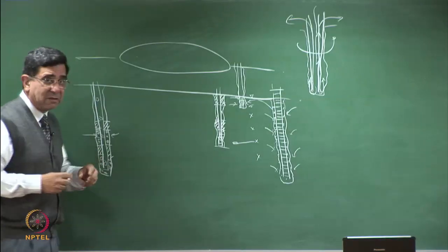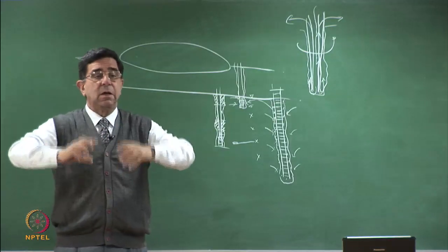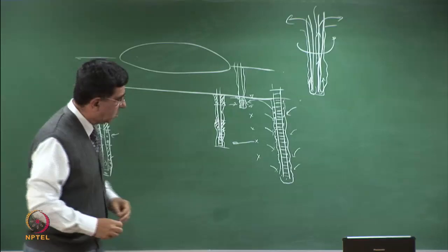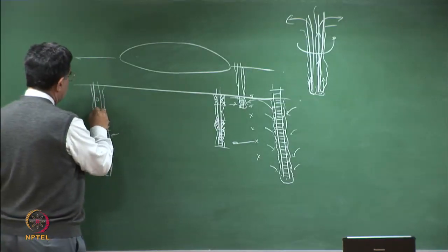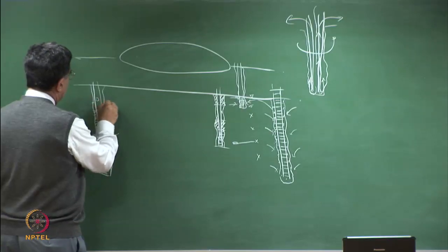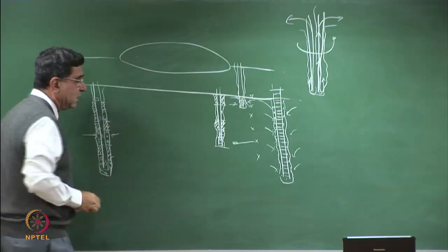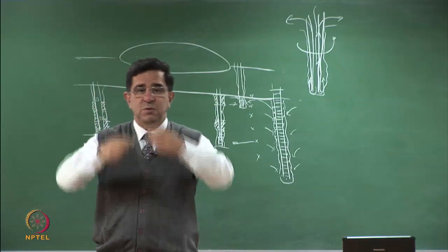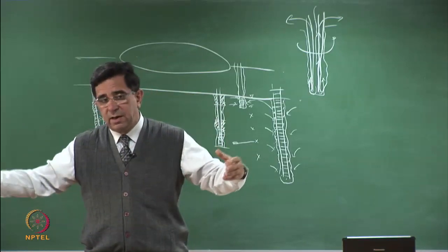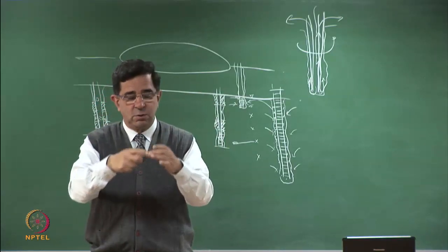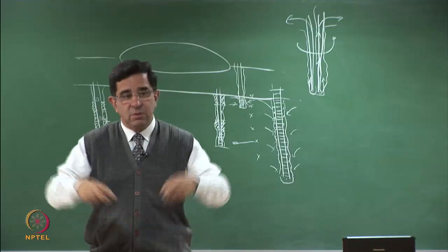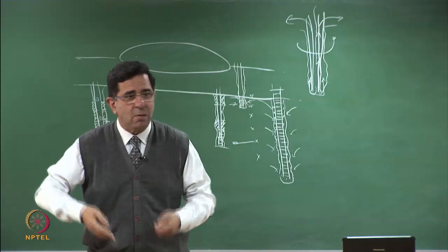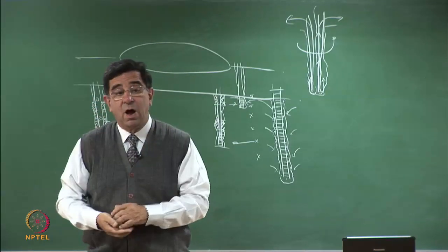So a multi-port device has got multiple levels of sealants in the annular space between the pipe and the borehole. That is critical. Then again you put gravel here, and then you put your bentonite seal. Do you know how they seal the annular space? How do you seal an annular space between the pipe and the soil outside? You have made an 8-inch hole, you put a 6-inch pipe inside it, you put the gravel pack all around it. How do you put the gravel? You just put the gravel from the top, it goes into the bentonite slurry which is there. How do you seal it then?